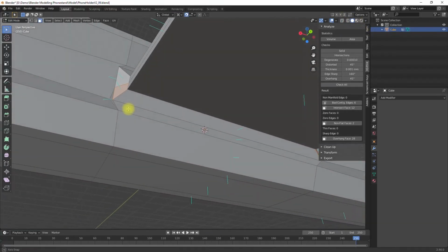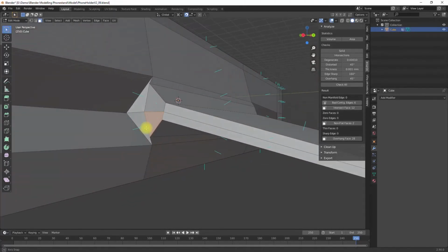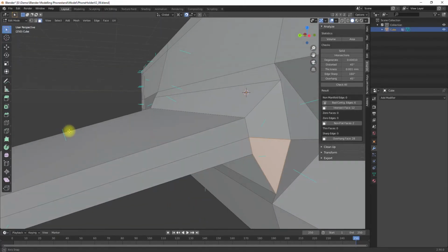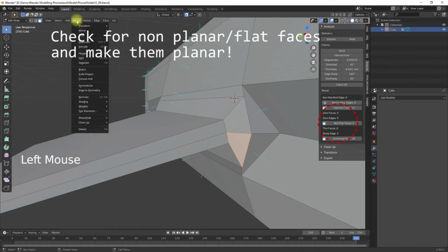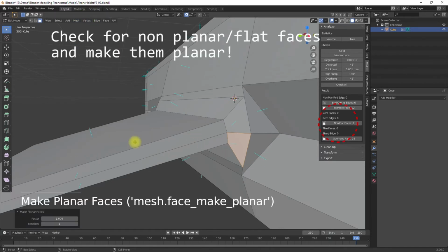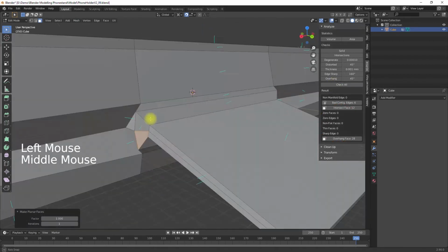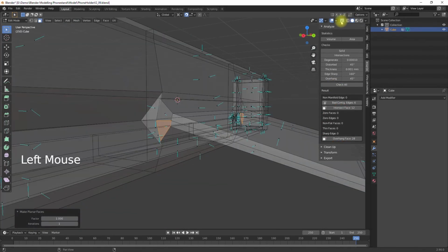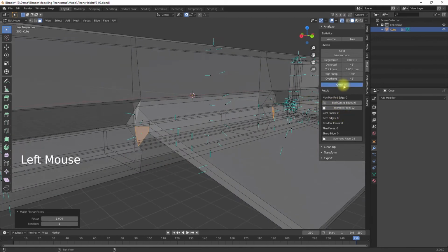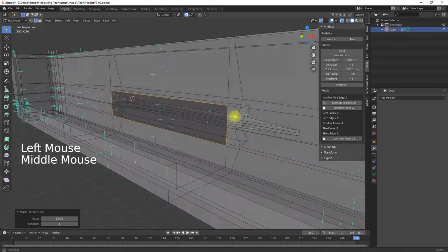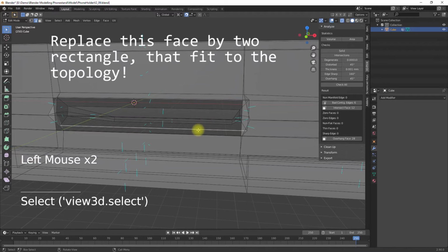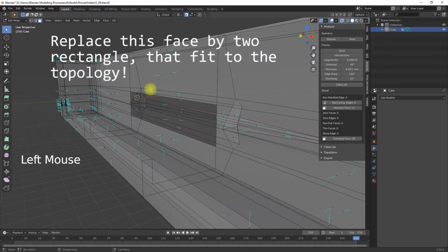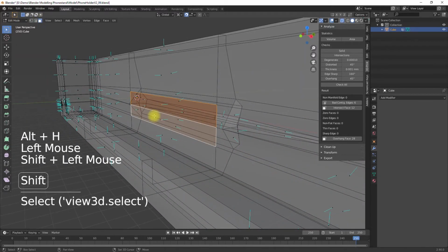There are some failures in our model generated by the Solidify modifier in the transition between the body of the model and the mounting bracket. To fix that, we have to correct the mesh manually, and for this we can use the 3D Print Toolbox to identify any failures in the overall geometry and use the mesh cleanup functions to get rid of these errors in the geometry of our model.